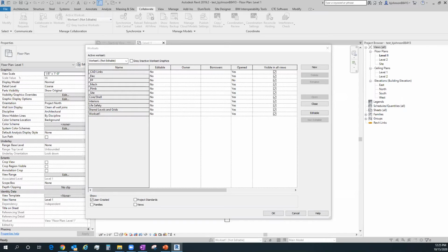And then the last piece is, once you've done model maintenance and you've reopened the file as a new local as a test, making sure that it opens correctly and there's nothing wrong with it, no corruptions from other files and whatnot, at that point I would notify the team that they need to delete their local file and the backup folder on their local machine. And then once they start a fresh file from the new central, their backup data and local file information, which is a different file size, none of that is coming back into the central file. So that's typically what I would do normally for what we call model maintenance.